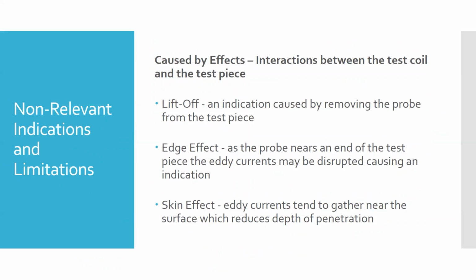But you're looking at the screen and you start to get near the edge, at first it'll look like a crack indication. We want to make sure we don't accidentally confuse it with a crack or a flaw indication. What I mean by that is if I draw our impedance plane diagram, which is the screen, we've got our screen here, and I draw our indications, and I'll use that absolute probe example again.